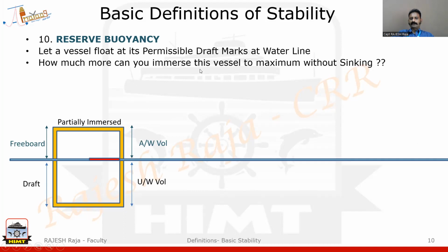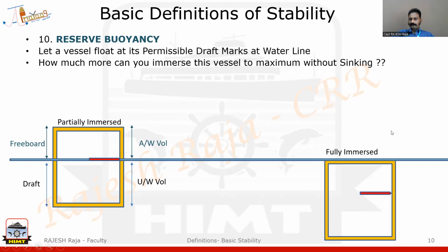How much more can you immerse this vessel to a maximum without sinking it? So going by the flotation principle, this is the condition. I'm fully immersed. That means now after this, I don't have any more volume to displace. So hence there's a high risk of sinking. Why? Because after this you add weight, then it goes beyond the displacement of the water which this body can push out. So this is the simple way of understanding what is reserve buoyancy.